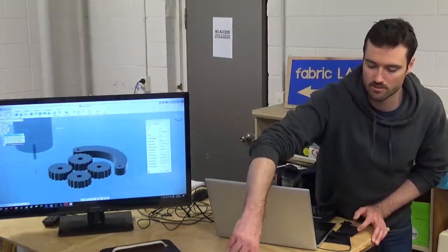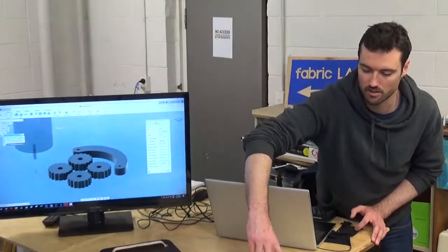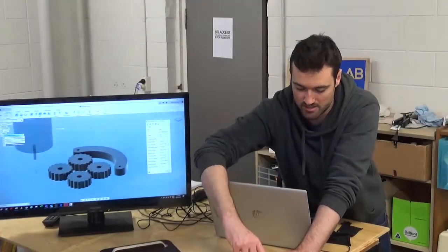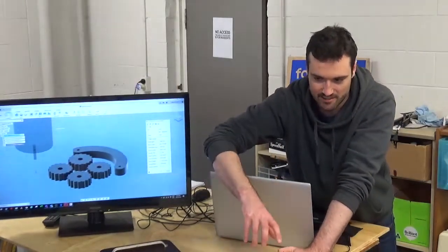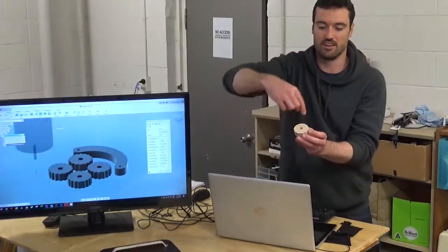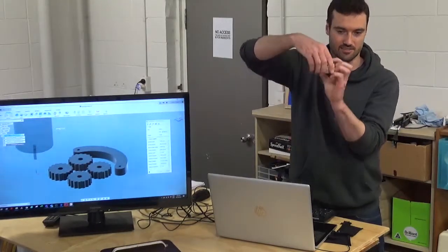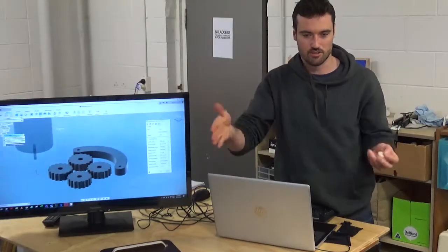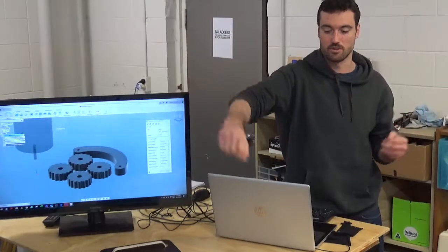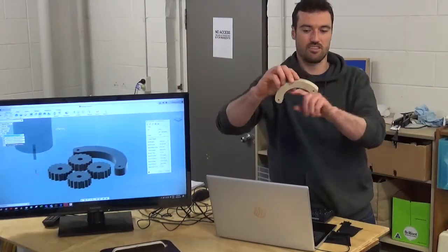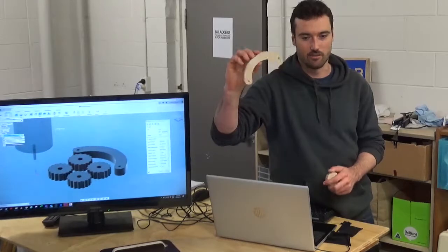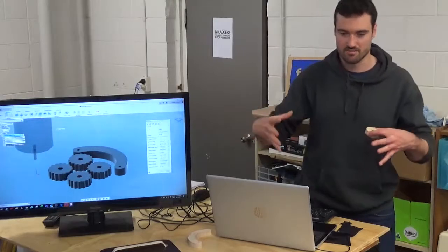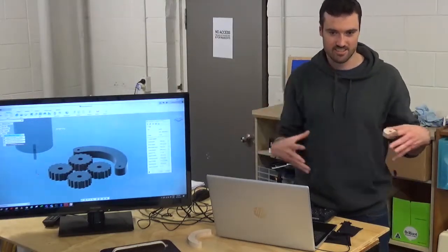Especially when we're doing something that's a circle, the other thing that's important to keep in mind is that if you put a screw in there to hold it still, it's actually in the center of the axis of rotation. So as you're cutting it out, it'll rotate and unscrew itself and fly out. Do you know what I mean? So when you're screwing stuff down, you want to try and minimize that and have your screws really offset. If we put 2 screws on that piece, it ain't going anywhere. So that should be fine. But you might still add tabs so the rest of the waste material doesn't start moving around.